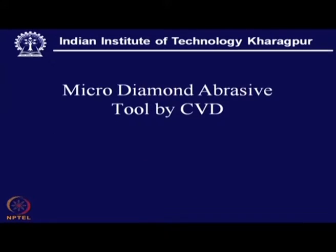Now comes the micro diamond abrasive tool by CVD. We know CVD technology for diamond. This is hot filament CVD. We can also use DC plasma arc, but what is important here is that it is not a continuous coating.